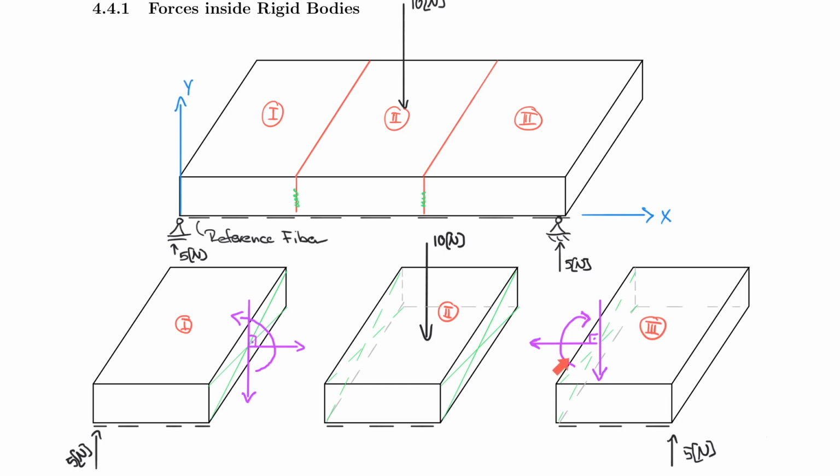Of course, I could have also put the arrowhead here on the bottom side, but there's a specific reason that we will talk about in just a little bit why this is rotating counterclockwise, where this one is turning clockwise. And similarly here, this is pointing to the left and this is pointing to the right. And the reason for that really is because we're trying to pull away from the surface and pull away from the surface. All right, so now with these three forces, we also have element 3 in equilibrium.